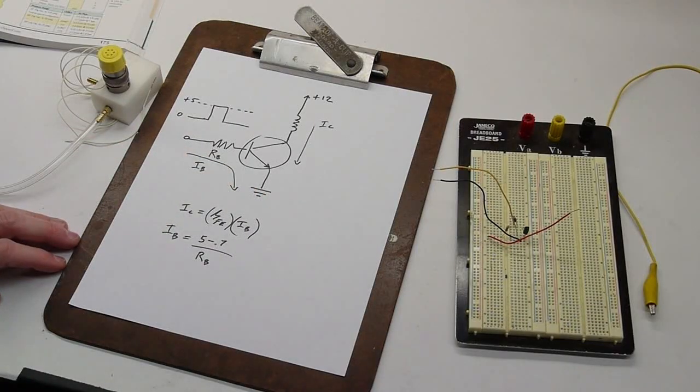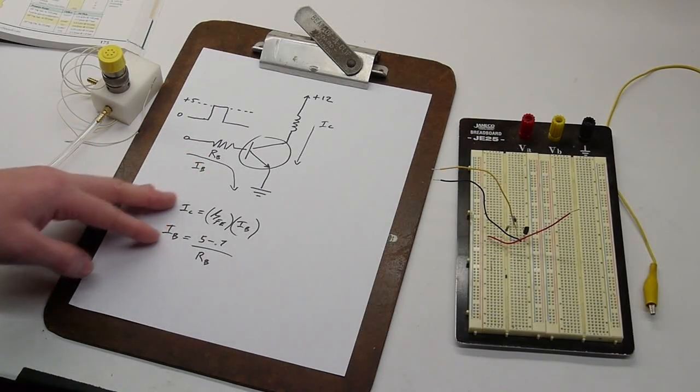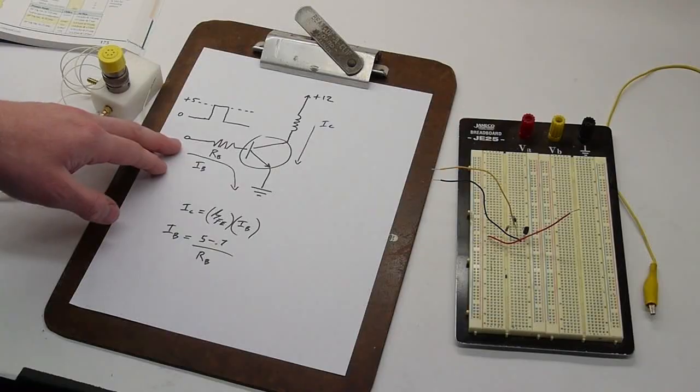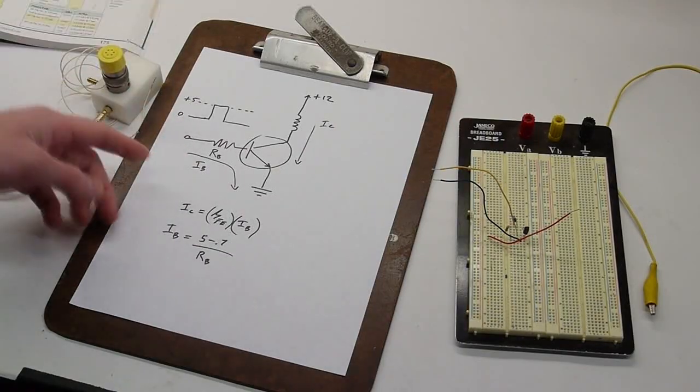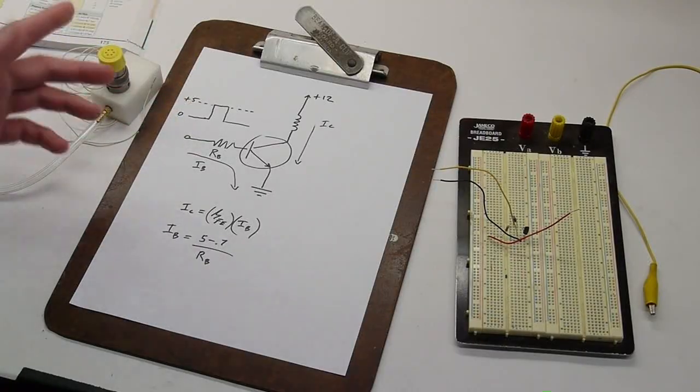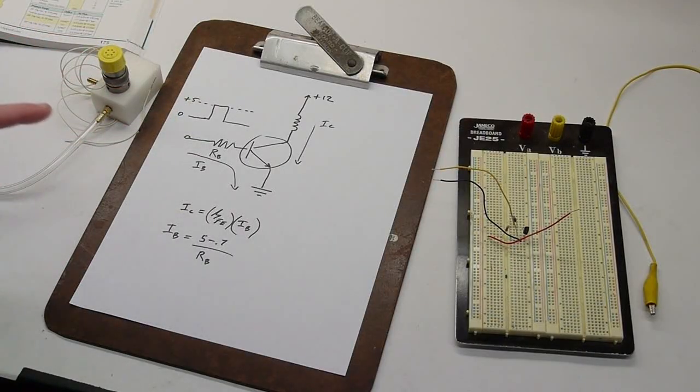to ground. So you're thinking, yeah, but I live in a voltage world. How do we actually get this thing to turn on and off? So we put this resistor here to convert our input voltage to a current. And you might be thinking, well, that's easy. I'll just use Ohm's law. 5 volts over the resistor value gives me the current. Almost. There's another little twist here.